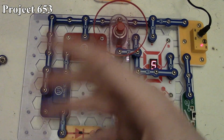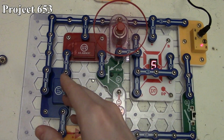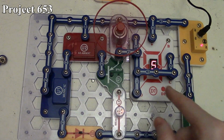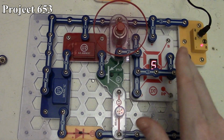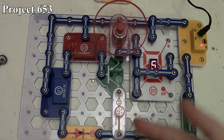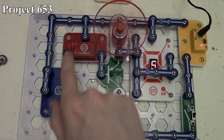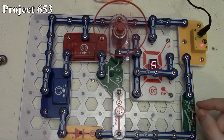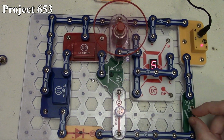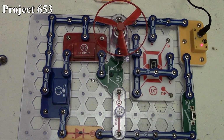It plays this little music thing, which is driving the alarm IC and everything else, and then when it completes, it stops and restarts, which is why we get that momentary drop when everything turns off and then starts again. Hence why they call it IC start and stop, because the music IC is controlling the start and stop of everything else in the circuit here. So that's how Project 653 works.